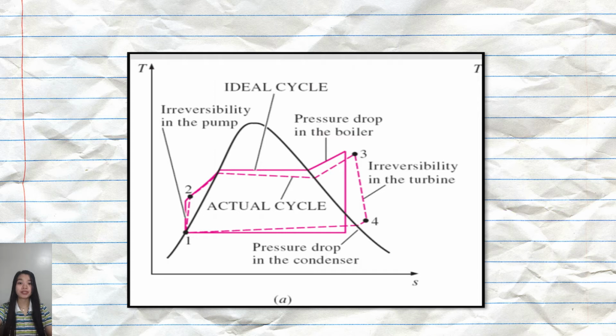to water droplets formation. As the water droplets condense, they will hit the turbine at a very high speed and the turbine will get eroded. The blades and efficiency of the turbine will be reduced. Solutions like superheating of steam are employed to overcome these problems. So to overcome the losses and get more net power output, some variations are adopted in the Rankine cycle.